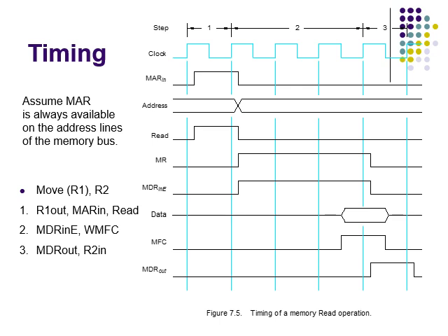When a new address is loaded into the memory address register, it will appear on the memory bus at the beginning of the next clock cycle, as shown in this diagram. A read control signal is activated at the same time as the MAR is being loaded. You can see it here.